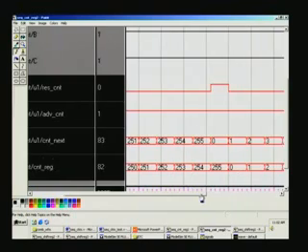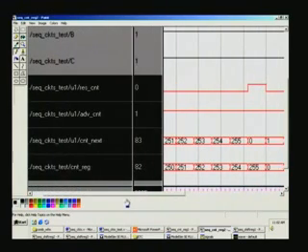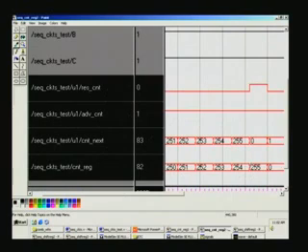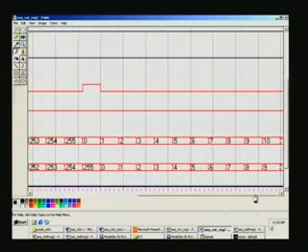And when you see here, it happens that 255 is here. This is for the counter edge. That's what we want when it touches 255, right? This being a combinational circuit, it goes high. You see, for so long as it is 255, it goes high. So this is nothing but the reset counter. So when it touches 255, the counter is reset. That's what we want. If you desire other than 255, you can put any other value straight away in decimal. That's the advantage of it. After that, again it folds back and resumes the counting, because it is an eternal counter as such. So that's how the functionality is.